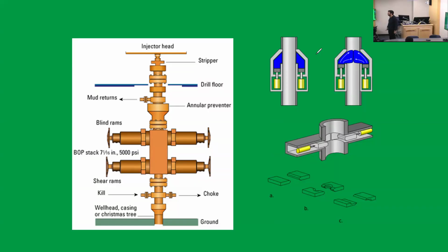Most of the times now they use both. It's the blind shear rams. The latter is better, to be safe. You cut and cover. Maybe, but that one will also spoil your pipe. But with the blind, maybe the kick might not be too severe. But it's better to always be safe. And if you're alive, that's when you talk about money.